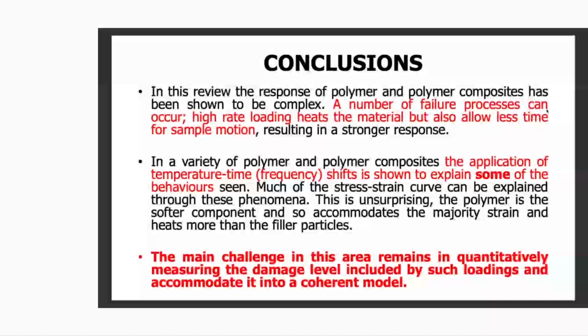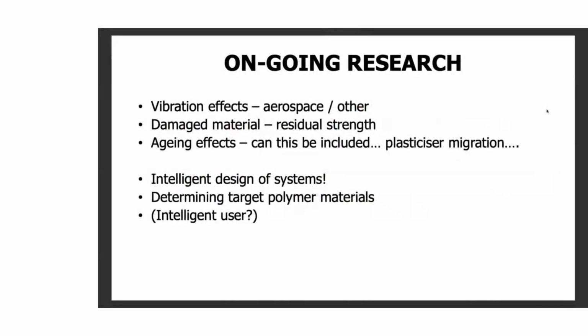So we feel we can do a reasonable job on predicting bulk properties and bulk properties of strain rate, but actual damage and cracking, and attention to things like adhesion between the polymer and the fibers or the granular filler, is still a thing we need to do. So there's still a lot of ongoing research out there. We have to look at vibration effects, say in aerospace and other areas, so low frequency repetitive loading.